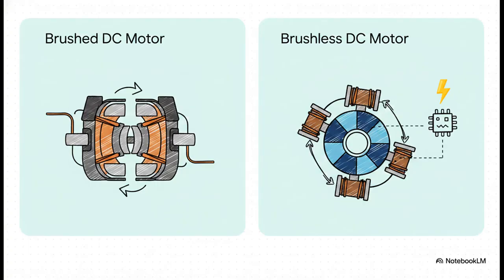Permanent magnet DC motors are incredibly popular, especially when you need strict control over speed or torque. Honestly, it's just notoriously easier to implement control systems using DC motors compared to their AC counterparts. Within this category, we're really looking at two main flavors. First up is the traditional brush DC motor. This uses exactly what we were just talking about: wound coils of wire on the rotor, fixed magnets on the stator, and mechanical sliding electrical switches. Those are the commutator and the brushes to constantly rotate that magnetic field.